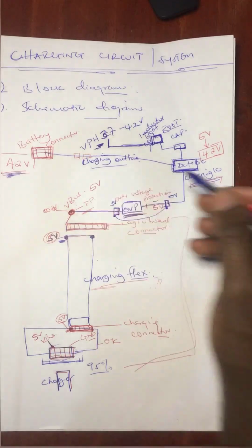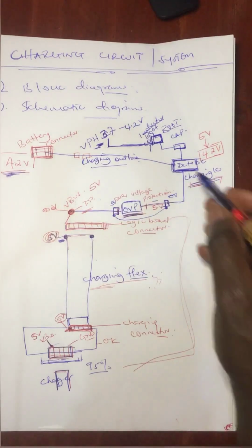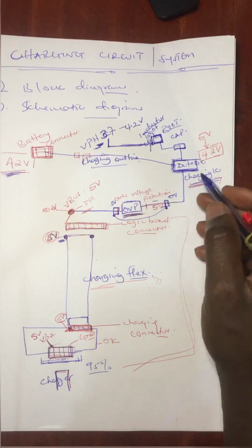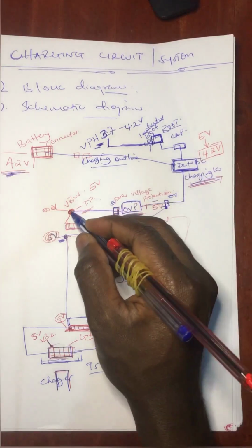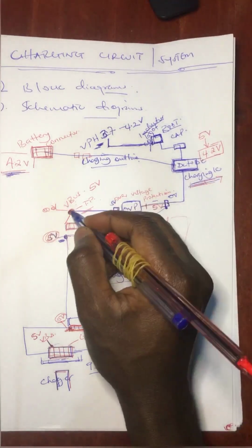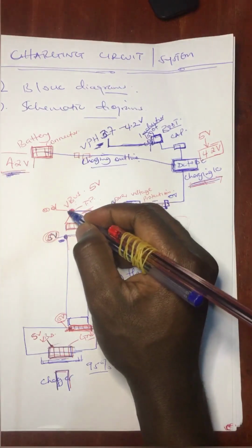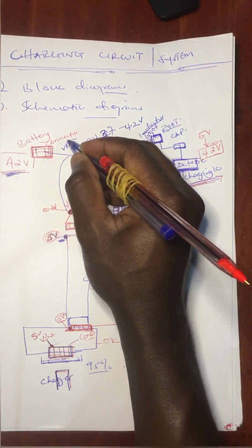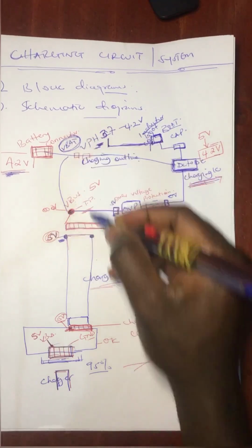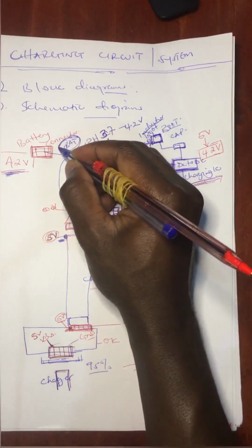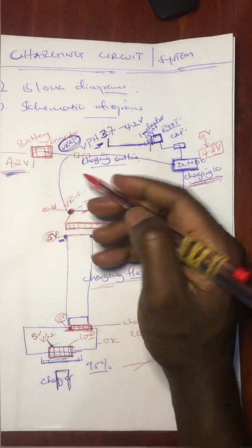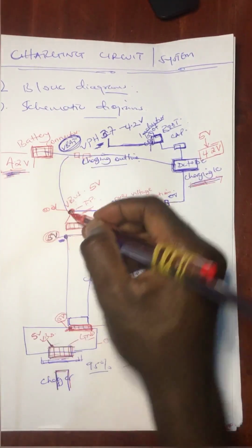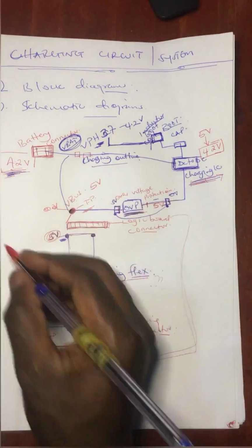If you cannot do that, or maybe you don't have the requirements to do this, you can take a jumper. The easiest way is to take a jumper direct from the VBus, the 5 volts, and you bring the jumper to the VBat. Okay, you take the jumper from the VBus to the VBat. Now, if you do this, it means you're feeding the battery direct from the VBus.